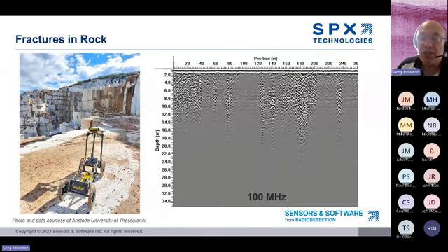If you scan a homogeneous or uniform material, there's no contrast, and therefore you don't get any GPR reflections back. Now, this is very rare, as most materials, even snow and sand on a beach, have some sort of structure to them that GPR often reveals. If we think about rocks like granite or marble, they do tend to have a very consistent structure, except for one thing: fractures. They tend to crack. And GPR is an excellent tool for seeing fractures in these types of rock.